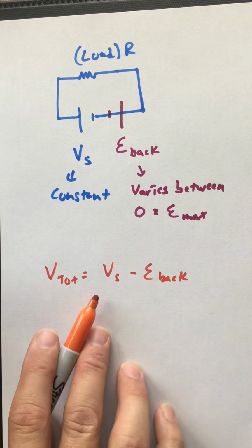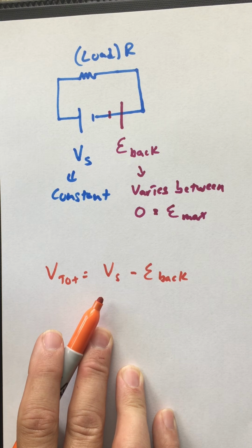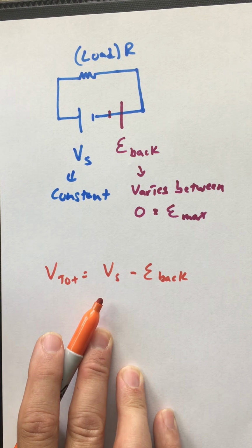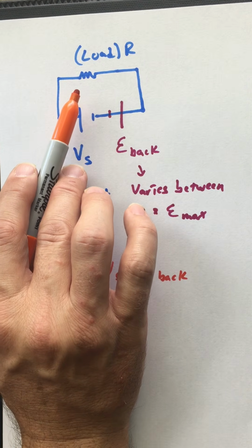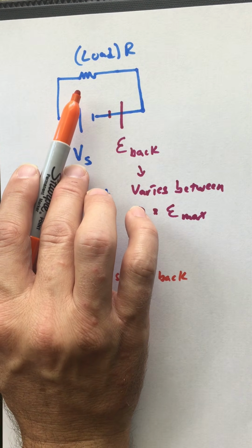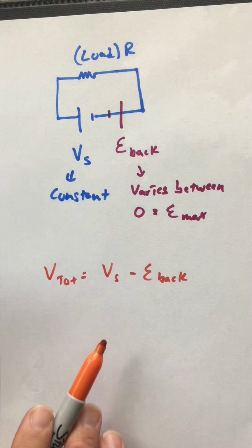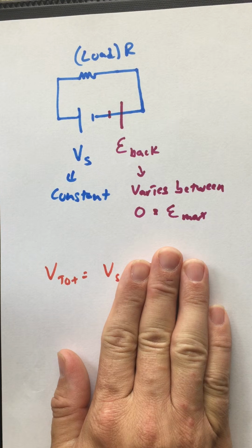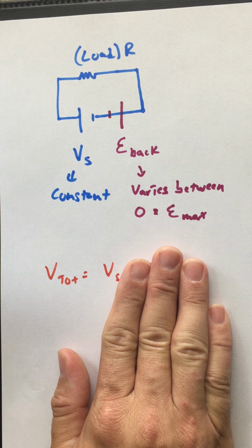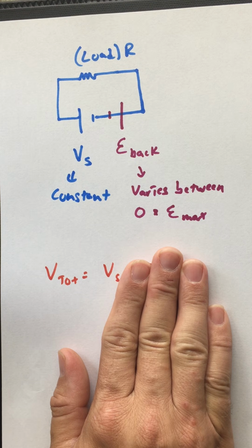That's good, because if you draw a lot of current, think of what happens to current flowing through a resistor, right? What happens to the resistor? It heats up. There's power dissipated by this resistor. So if I'm drawing a lot of current, if this back EMF didn't exist and my source voltage is very high, I'm going to burn up my electronics really, really quickly. And in point of fact, that can happen.